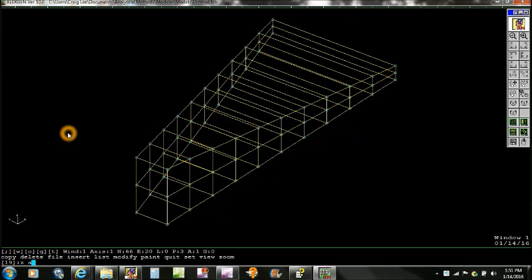I'm going to change the view direction here, and I'm going to copy combine. That's a command that will copy both elements and nodes combined. I'm going to do that with elements 1 through 20. That's all that we had. And we'll do that 20 times around the perimeter.